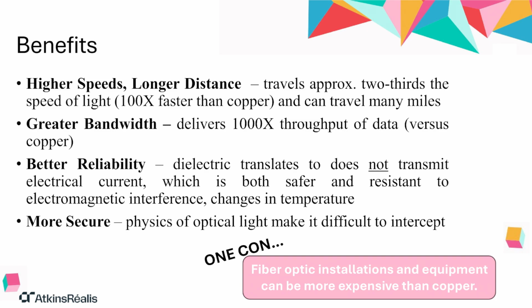Definitely. And finally, it's inherently more secure. Because the data is light trapped inside a glass strand, it's incredibly difficult to tap into without physically cutting or damaging the fiber. And if you do that, the signal loss is usually detectable immediately. Unlike copper, where you can sometimes passively induce a current to eavesdrop, you can't really do that with light in a fiber. Speed, bandwidth, reliability, security.